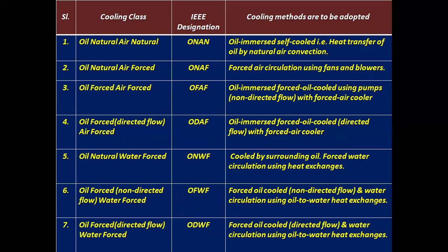Oil natural, air natural, that is ONAN. Oil immersed, self-cooled, that is heat transfer of oil by natural air convection. Number two, oil natural, air forced, ONAF, forced air circulation using fans and blowers. Oil forced, air forced, OFAF. Oil immersed, forced oil cooled using pumps.